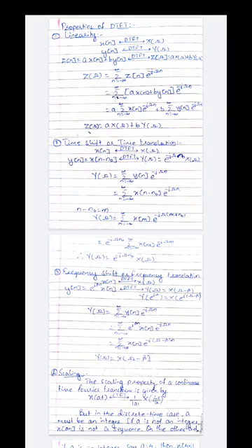Now if you observe both the summations, they are the standard definitions of discrete time Fourier transform. So the first summation can be written as X of omega, which is the spectrum for the sequence x of n, and second summation can be written as Y of omega, which is the spectrum for the sequence y of n. So the proof for the linearity is Z of omega is equal to a X of omega plus b Y of omega, which is the required proof for linearity.